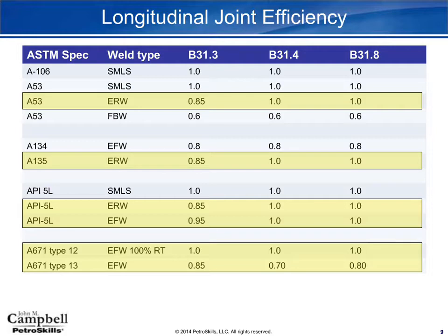And so there needs to be some sensitivity here, independent of your project, as to where that is being specified and carried through all the way from the engineering through procurement, supply, and installation. Joint efficiency is a big factor that affects our design, and tracking subtle details such as the type number or grade or the type of weld joint that's on that pipe is an important part of the specification process.